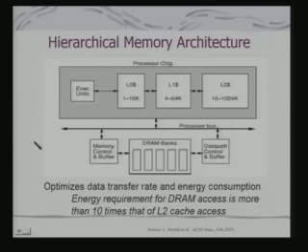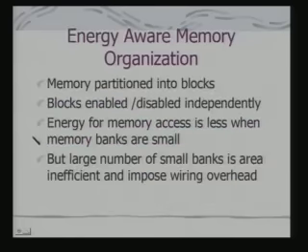In fact, this concept of energy leads us to what we call energy aware memory organization. And typically, the memory is partitioned into blocks. Okay. Blocks are enabled or disabled independently, and energy for memory access is less when memory banks are small, but a large number of small banks is area inefficient and can impose wiring overhead. So, energy is an important consideration for all embedded systems and particularly battery powered embedded systems.